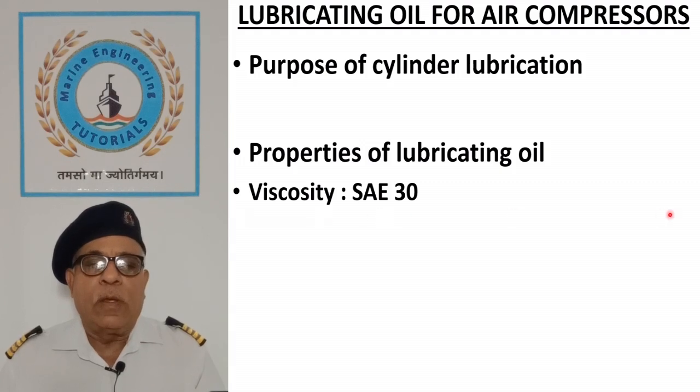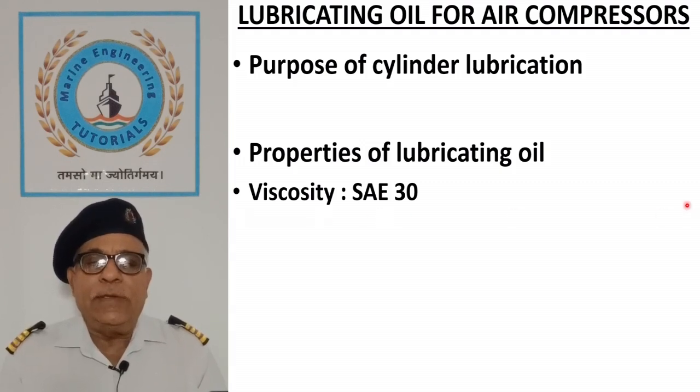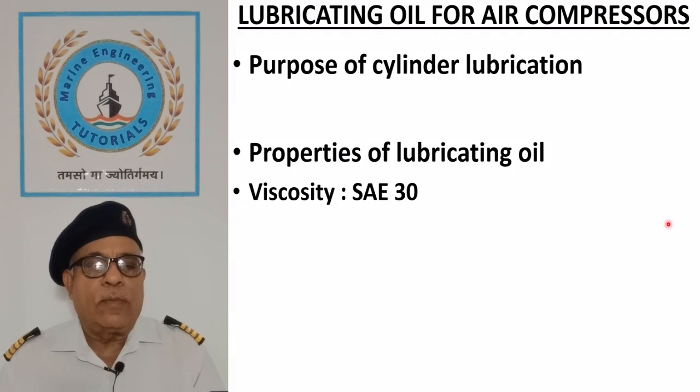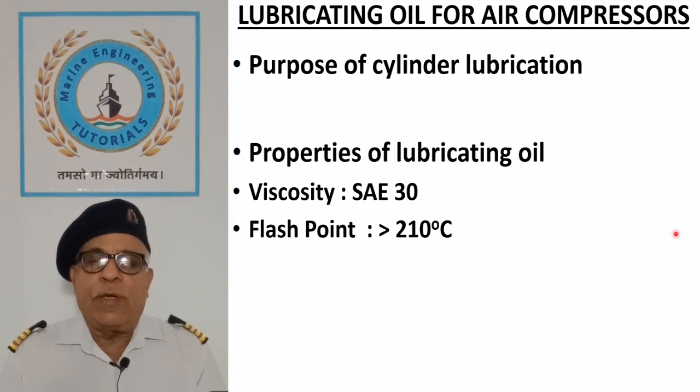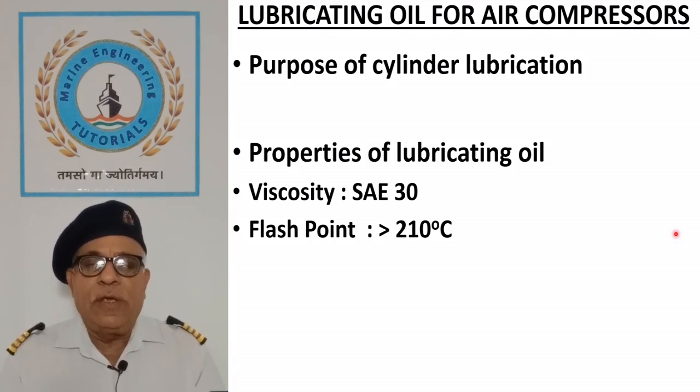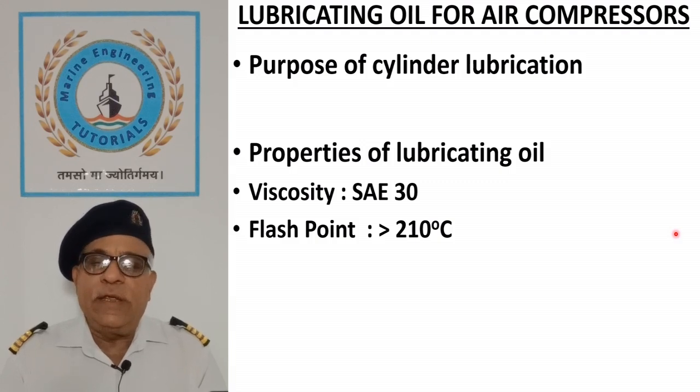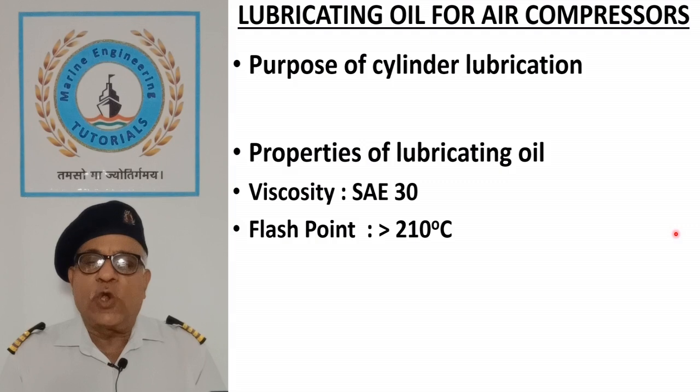Viscosity. Correct viscosity to maintain the required film thickness is usually grade 30 as per Society of Automotive Engineers. Flash point. Flash point of lubricating oil should be greater than 210 degrees Celsius because the compression temperature is restricted below 200 degrees Celsius, so that oil does not vaporize and leave the carbon behind, which causes fouling of the valves.